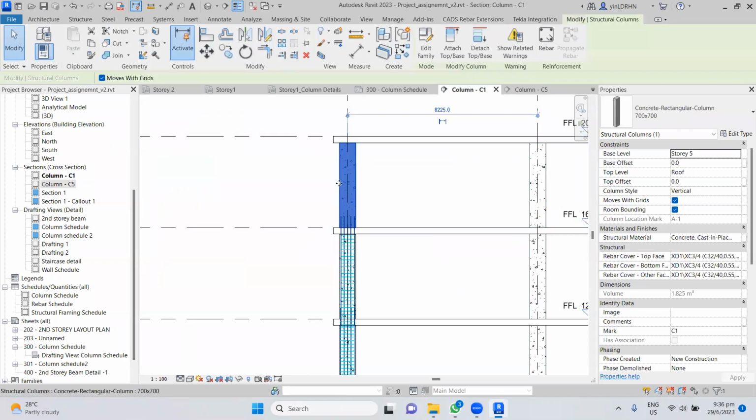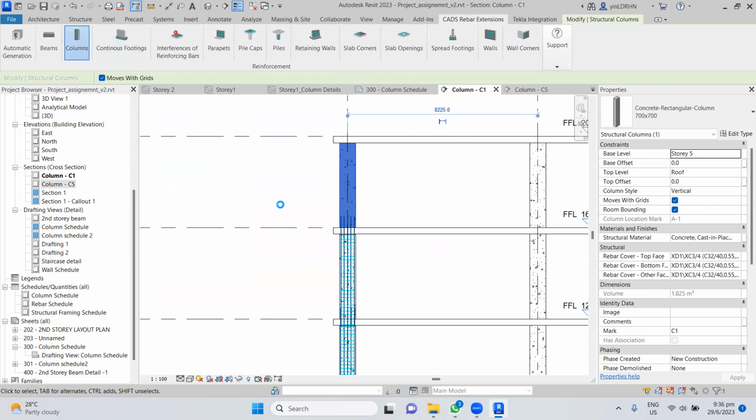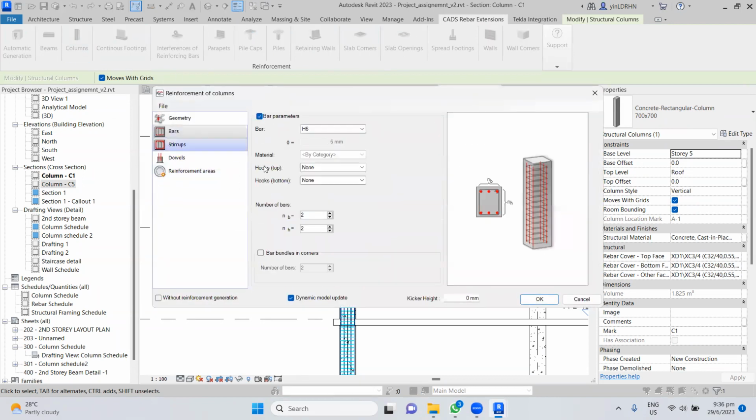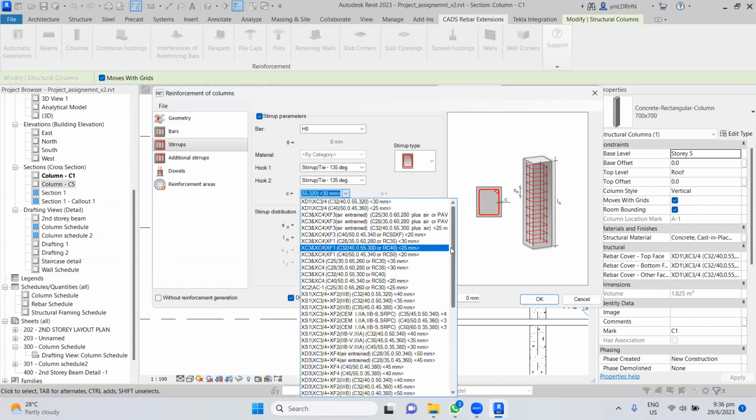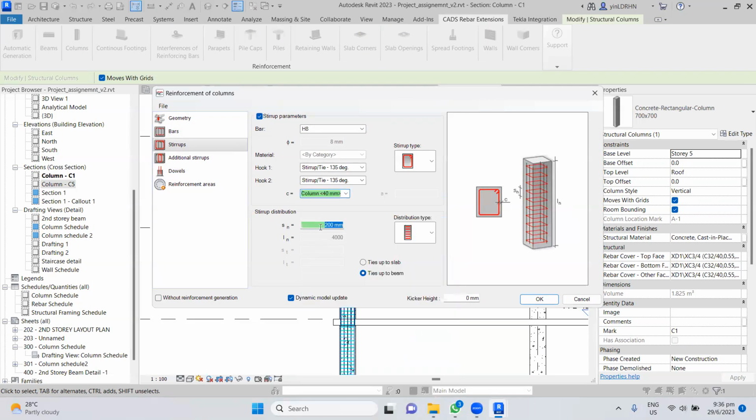So we go under here. Okay, this floor we don't need a double. So the top rebar we have to anchor into the slab. So go to column. Same thing. And the diameter. This one change to the column. 150 spacing.